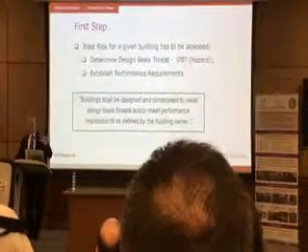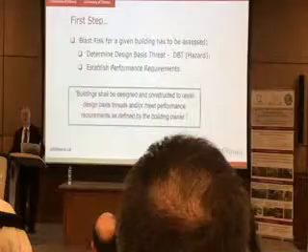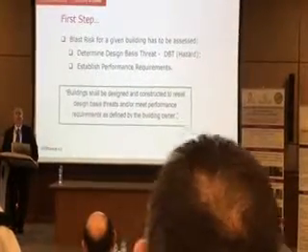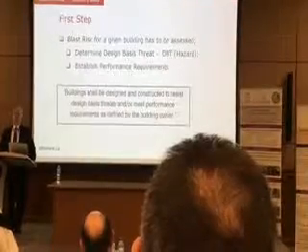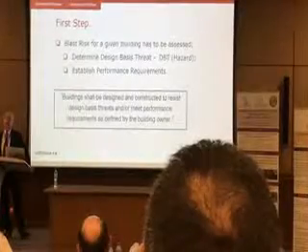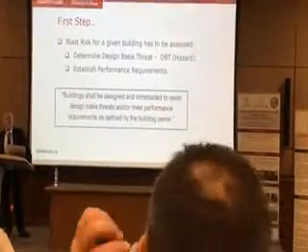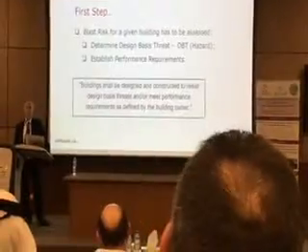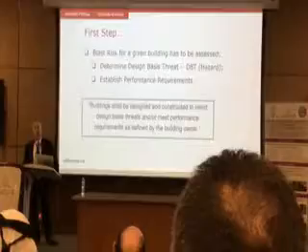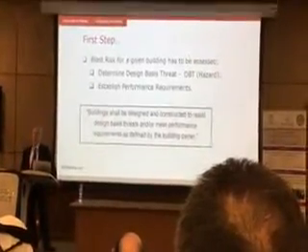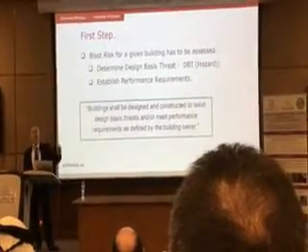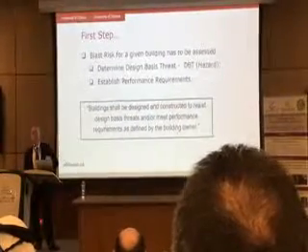First step is, again, to go outside of our typical expertise and define the threat. So in earthquake engineering, what do we do? We go to seismologists and they give us ground motions, right? As structural engineers or civil engineers, we don't know how to get ground motions. They develop them, they give them to us as tools. Building codes specify spectral accelerations, and those spectral accelerations were developed by seismologists. And then we take the maximum spectral acceleration and design our building.